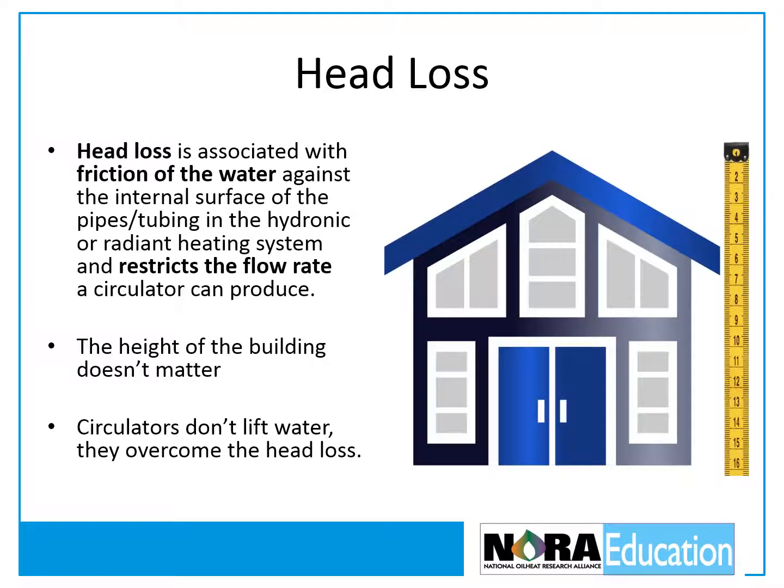The height of the building is not considered when sizing a circulator. The circulator doesn't lift the water to the top of the system. System pressure does that. The circulator only overcomes the head loss.